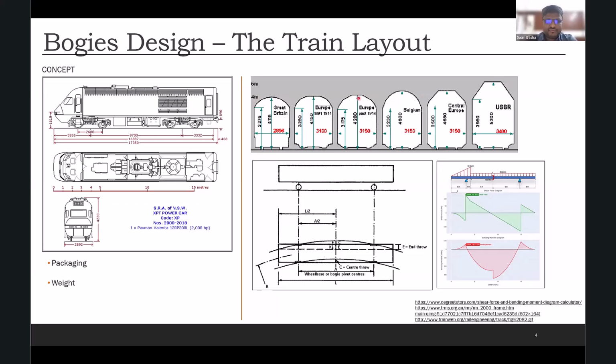Now, when it comes to where to space the bogies, here in this locomotive, for example, you have spaced it at around 9700 mm. So what are the parameters which will tell how much we need to space it apart? Two things mainly come into the picture. One is the strength of the underframe. Of course, you can see the right side picture here. Not going into much detail, this is the analysis that we do of the loading that is going to come on this structure, and then, keeping at a certain distance, what are the loads that this structure would see, and is it still within the limits or not. So we try to place the bogies so that they completely balance this load.